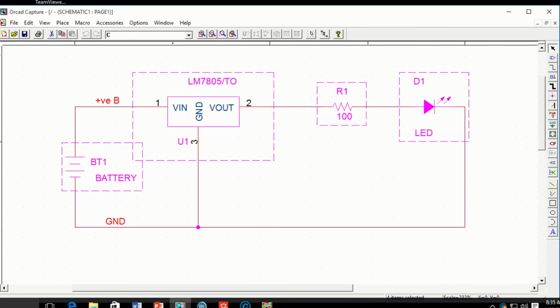The next step is to generate a layout netlist file. However, some steps are required to complete first: to annotate the design, and to perform the electrical and physical rules check on the circuit. This task can be performed using the Tools toolbar or using the Tools menu.